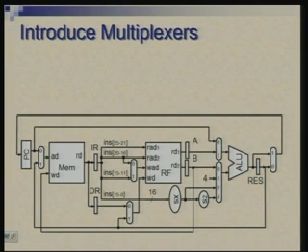Again, I have omitted the jump instruction. Now, as we have come from single cycle data path to multi-cycle data path, what we have got is a much faster clock. The clock period now needs to accommodate not the entire operation of one instruction, but one specific micro operation.